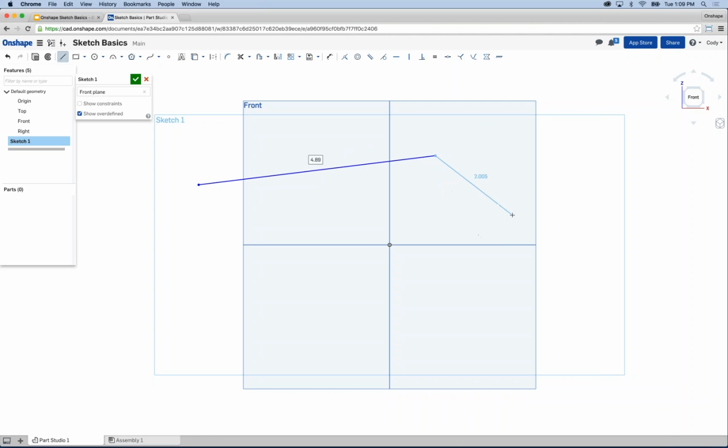Okay? Now if you don't want that line, remember you can always use the escape key to get out of the active command. So just a tip, the escape key is very useful for getting out of a command that you no longer want. So again, two left clicks create a simple line. The default behavior in that case is to construct another line after the last one. Okay? And if that's what you're looking for, it's a very easy way to do that.